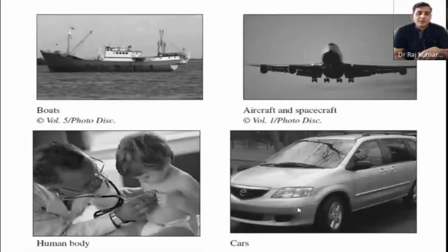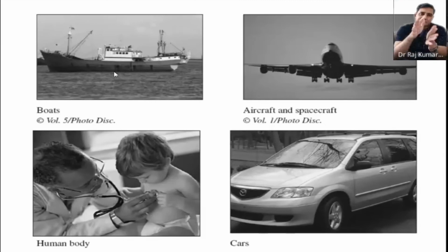Now there is the designing of your ship or your floating objects. The design is based on the buoyancy force, the Archimedes principle. You also want stability, so that in case of a slight change it should not topple down. Stability is calculated in terms of metacentric height, that is, your body weight and the center of gravity, and these should lie in the same line, correct? Just to make it stable, right?